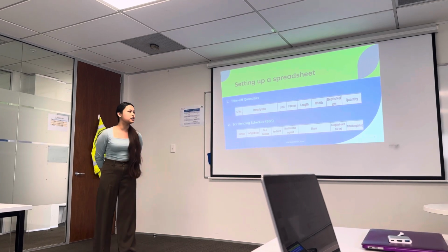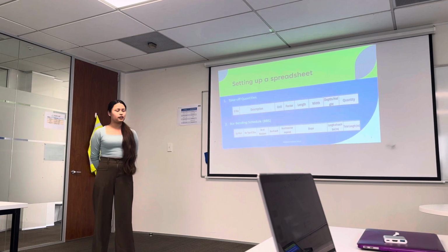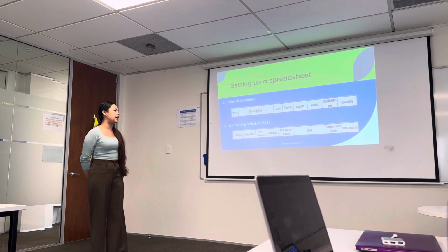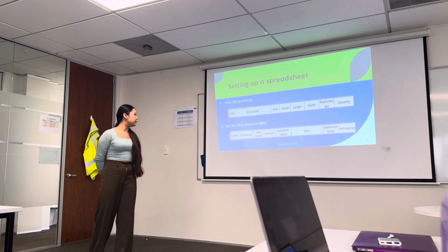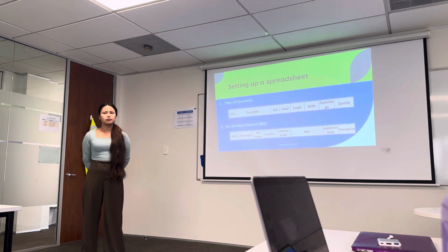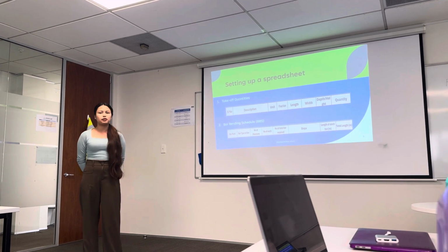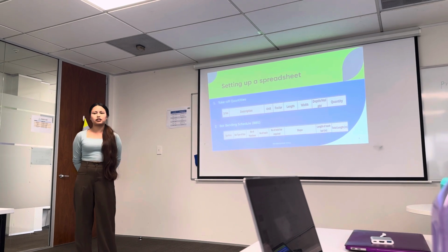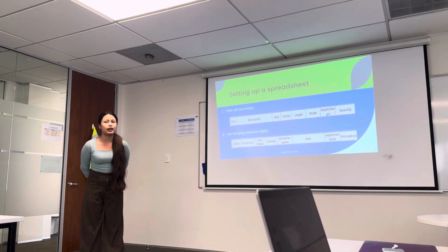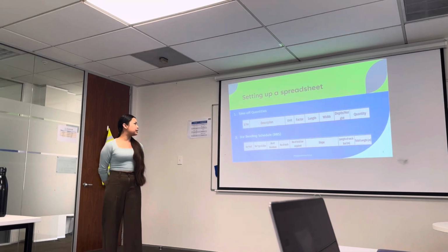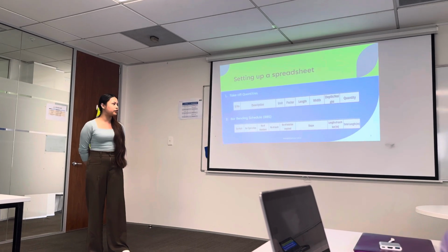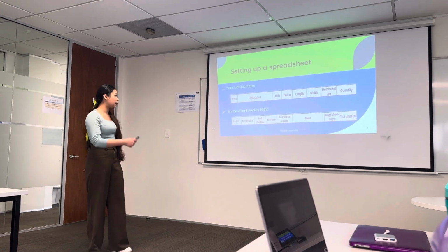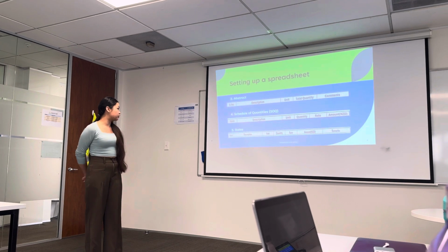For takeoff quantities, we have to mention the serial number and the description, unit, factors, length, width, depth, and quantity. After that, for bar bending schedules, the bar mark, bar type and size, number of members, number of each, number of total bars required, shape, length of each bar, and total length. We have to accurately set up the spreadsheet because we are using different types of descriptions and different types of format for different takeoffs and quantity takeoffs.